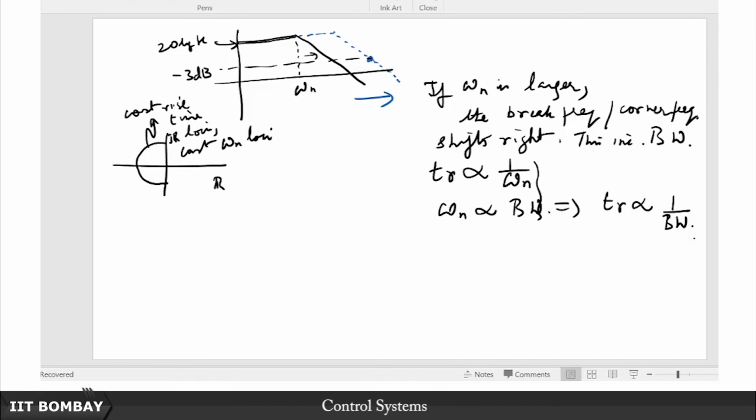So here also just permit me that laxity, and allow me to just deal with the second order system. In terms of the second order system, I have explained to you that the rise time decreases with an increase in the bandwidth. So if your user who is specifying the performance metrics is fond of time domain specifications, he or she might say I want a rise time so and so. On the other hand, you might have heard of bandwidth more often than rise time, right? You might have heard of bandwidth even before you attended this course. I am not so sure that you had actually heard of rise time before attending this course. So bandwidth is a more common terminology that appears in layperson's parlance.